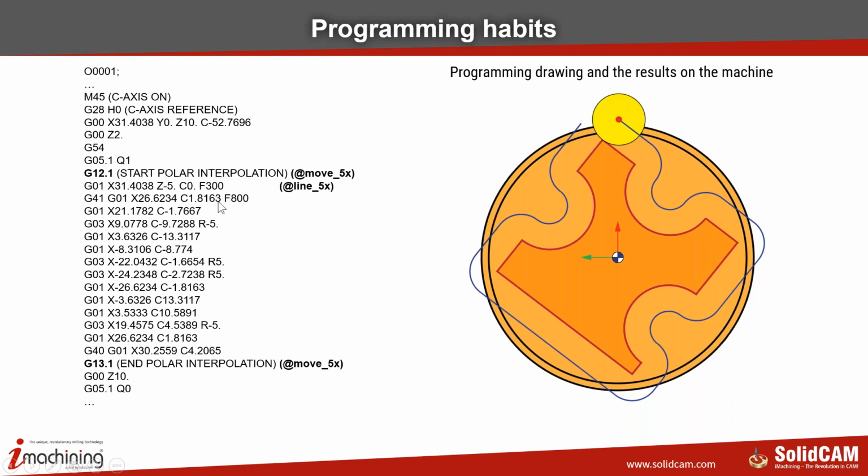What you should know is that it depends from control to control and settings. This angle, how you calculate it, can be positive or negative. I will also talk about that later. But what is also important is that the X-axis can be doubled, which means it's a diameter, or it can be radial. In most cases I've seen radial, but in this NTX 2000, which will be my example, it is actually doubled. So all the X-axis values that you see are actually doubled.